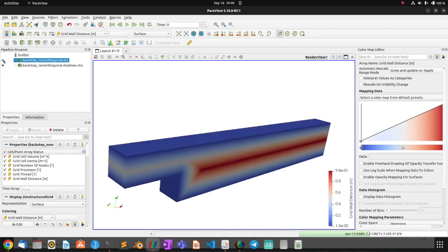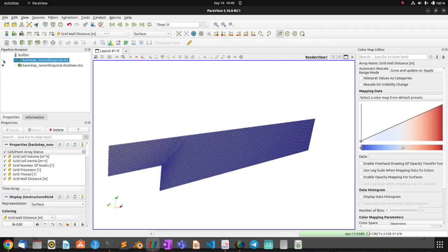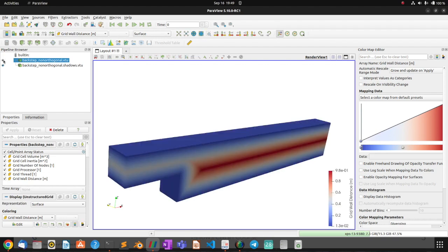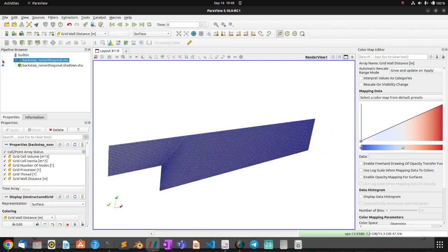Since it's a periodic boundary condition, it's implemented intentionally in this way in the code to represent one domain because the other is copied from it. It's basically copying the values from this phase to the other one as it's a periodic boundary condition. So that's why it's called the shadow, because it's the shadow of this surface on the other side.